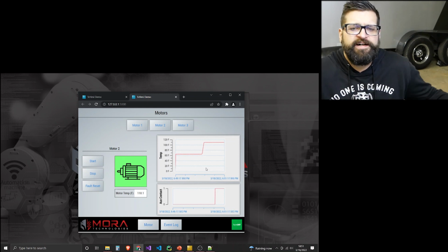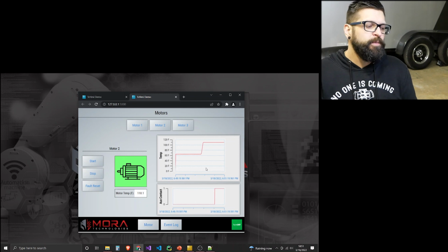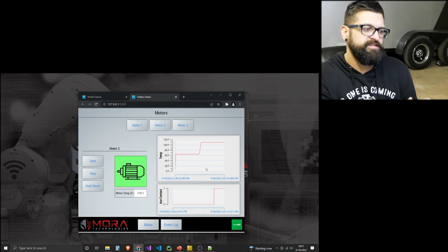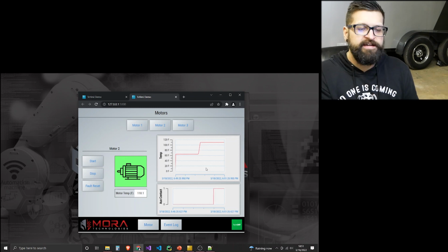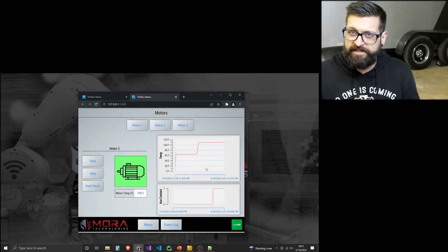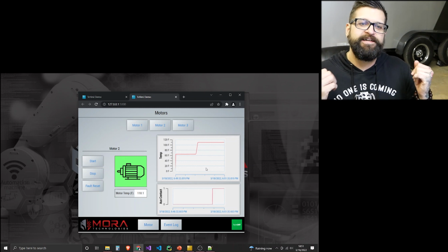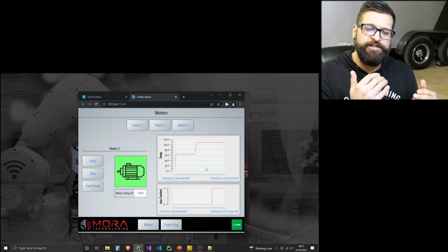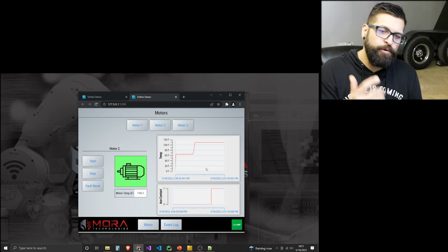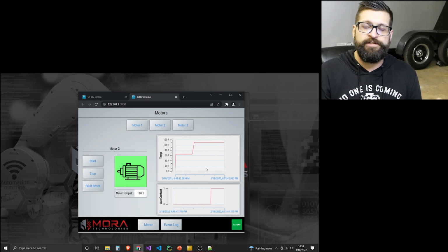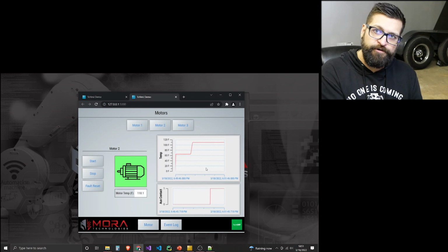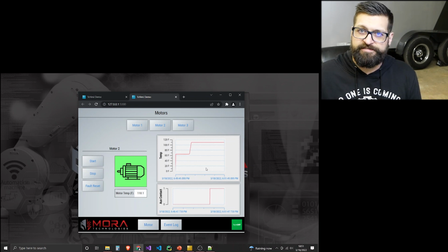So if we've got 10 motors or 100 motors or whatever, we don't want to have 100 instances of charts and user controls and all these things, because that's a whole lot of overhead. When we're trying to mass produce an OEM machine, we don't want to have to pad that price into a higher level PLC, more RAM, more cores, because with Beckhoff, as you move up in performance level with your hardware, your licensing scales also.